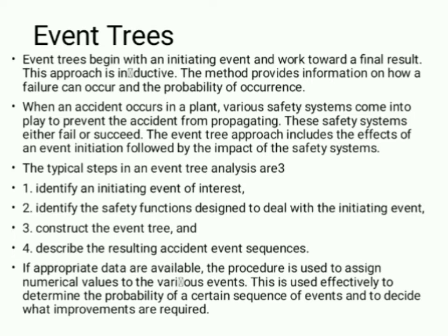Next, we have to construct the event tree, and after constructing it, we have to describe the resulting accident events and sequences. So there are three to four steps involved. First, find the initiating event; second, identify the safety functions designed; then construct the event tree.